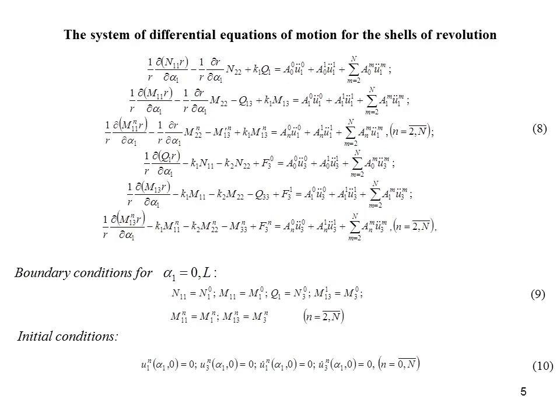An energy-consistent resolving system of dynamic equations for metal plastic shells of revolution and the natural dynamic boundary conditions are derived by minimizing the total energy functional of a shell as a three-dimensional body. By supplementing the obtained relations with the necessary number of initial conditions, we obtain a closed system of equations to analyze unsteady processes of deformation and strength of composite cylindrical shells loaded with an internal pressure pulse in a non-classical formulation.